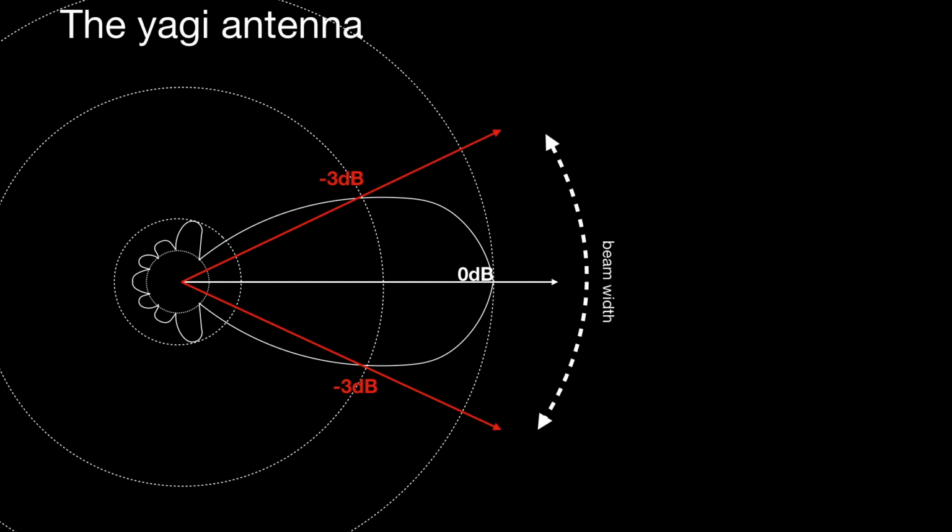Make sure that you don't confuse beam width with bandwidth. These are entirely different concepts. Beam width here is the half power points, not like bandwidth, when you're looking at the Q for filters and things, although it is similar, I suppose, but it is conceptually different. This is a physical rotation of the antenna through half of the beam width. If you imagine that on the diagram, you would see that you would be getting only half the power to a receiver located somewhere on the right-hand side of the screen.